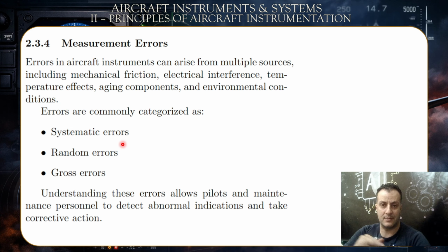Why? Because the current is now penetrating properly through this conductor. So at times due to vibration it would separate, acting as an open circuit on the electronic plate, and at times it would be working properly. Why? Because it's touching and separating. So this led to false measurements. It brought down an airplane. So again, that would be a kind of random error.